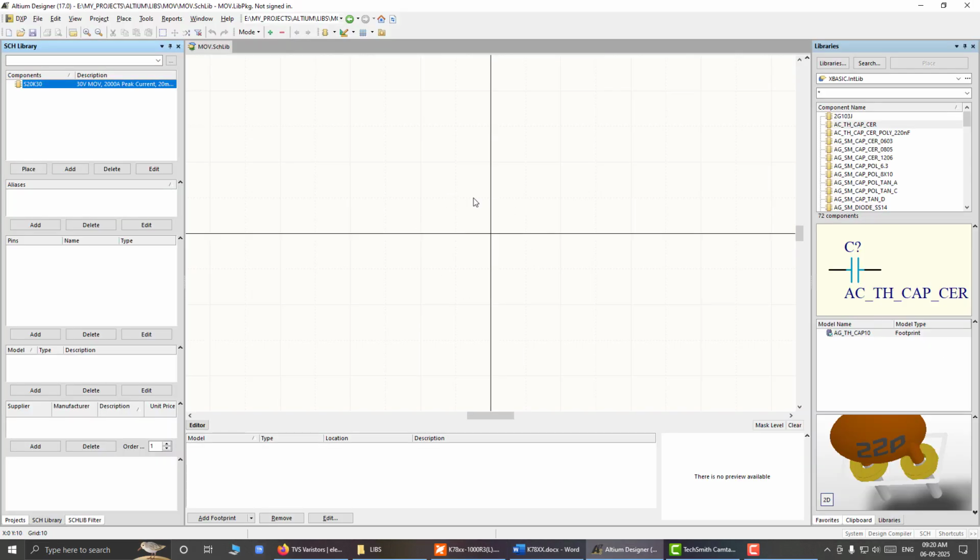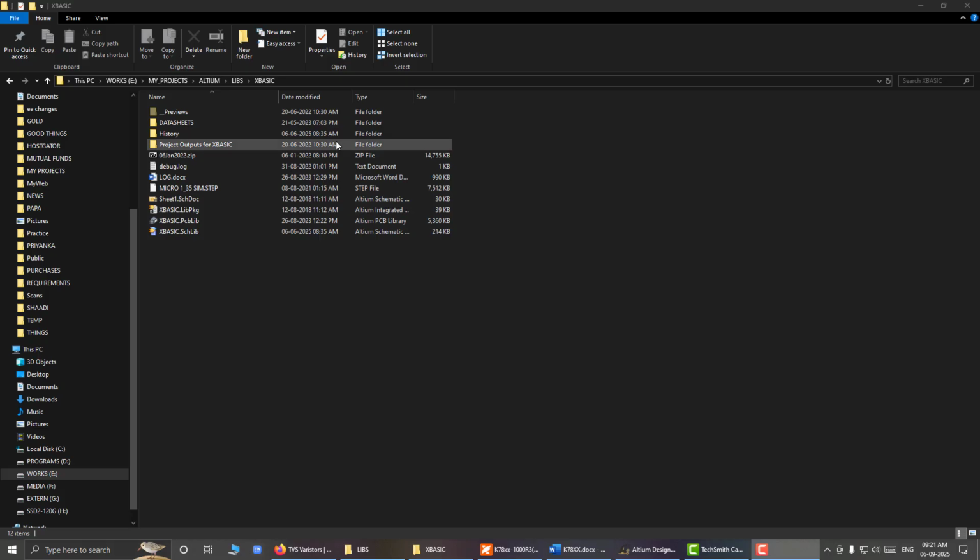During drawing you need to be aware of the scale, you should not draw it too large or too small. So generally you have to consult a library first. So just open up a standard library that I have provided, for example this XBasic, and edit the symbol for this capacitor or any resistor. So get the idea of scale. So let me open one of these. So here is my XBasic library that contains all basic electronics components on my file system, my hard drive.